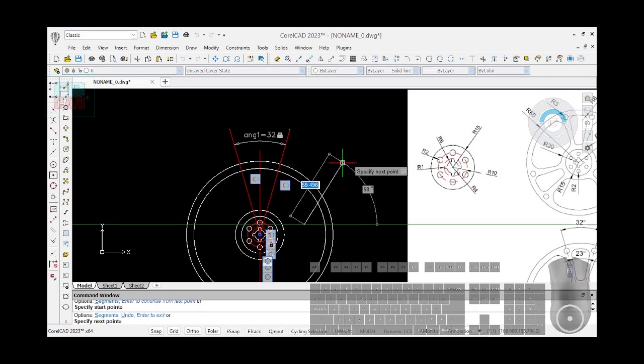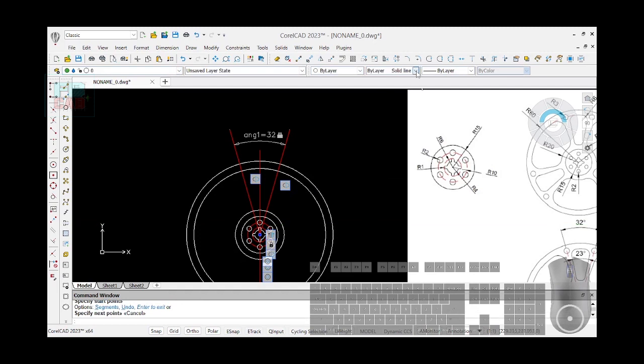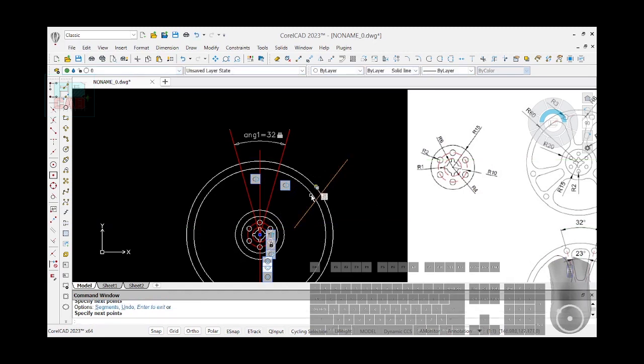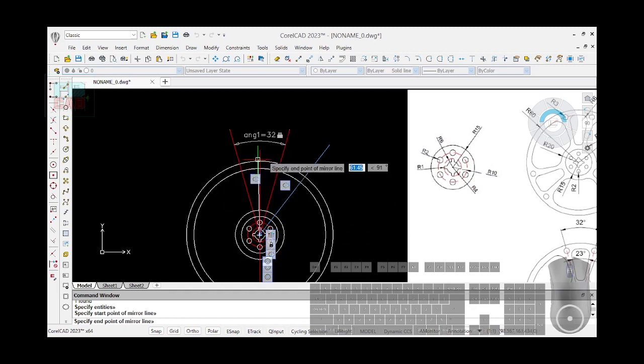The same procedure that we did earlier on. But this time around it is going to be a proper line because we're going to use it to construct what we have in here. So I'm going to have it here, here, enter. Then geometric constraint, coincident rather. This line and this to be coincident. Then I want to mirror it. I'm mirroring this along the horizontal line.